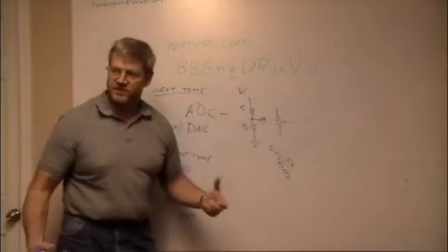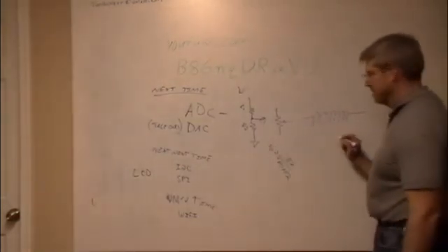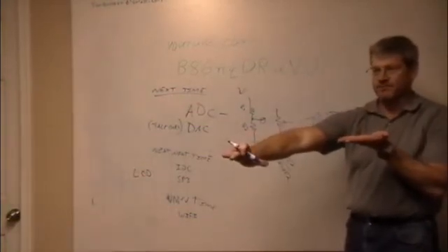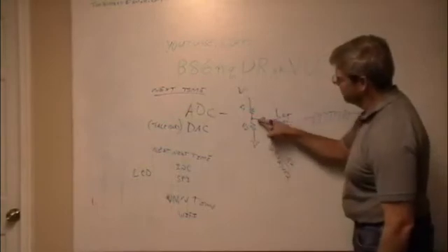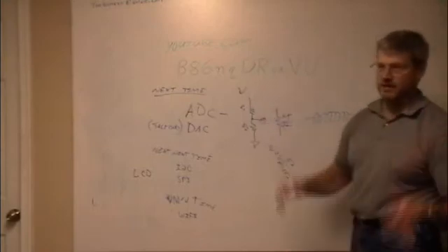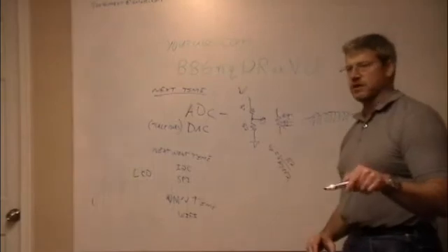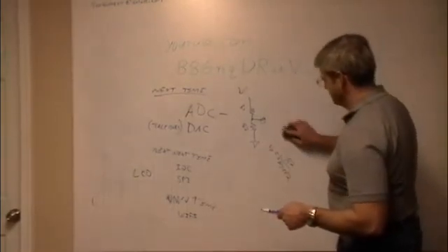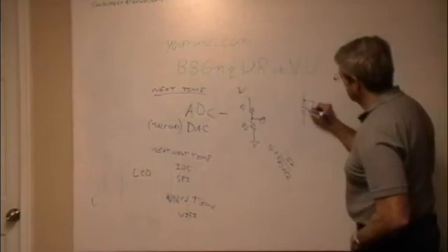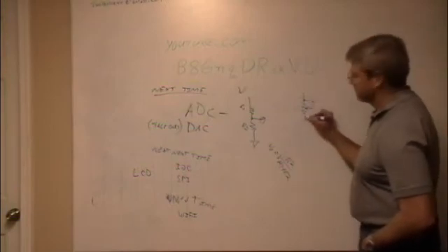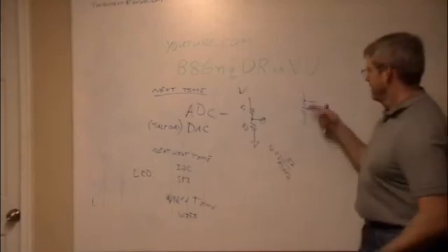So what a potentiometer is physically, often it is a coiled up wire with some resistance, and it actually has a little metal wiper that slides across that wire. So as it slides, pictorially it comes up here, or it comes down here. So you can come all the way down to basically 0, or you can come all the way up here to 10K or whatever the value is. So a rheostat, that's what they used to call them, a variable resistor, is effectively this very same thing that is tied like that. If I come all the way down here, it shorts across and the end-to-end resistance is 0 ohms. If I bring it all the way up here, then it's effectively the whole resistor, so the end-to-end resistance is the whole value, and if it's halfway in between.